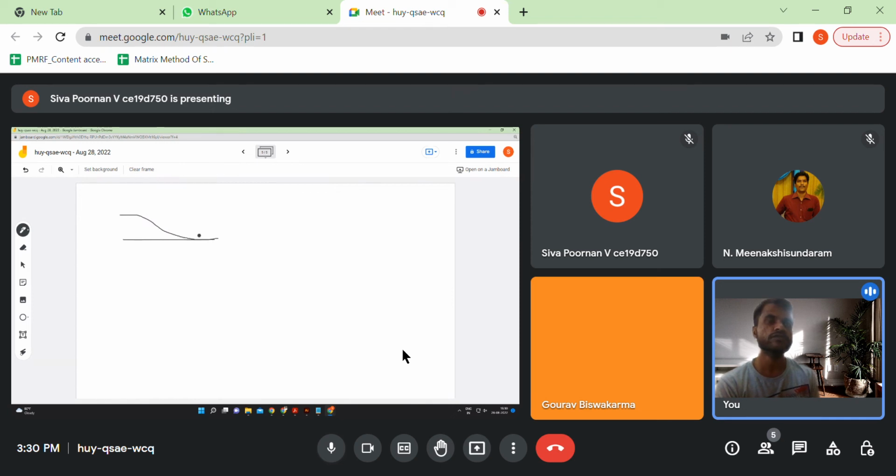Okay, now can you see there is a symmetry about the center? A kind of symmetry, because deformation wise this portion looks very same as this portion as well. Not displacement wise. Displacement is an absolute thing. A deformation is a relative thing. So basically I'm saying that if I take this portion and then somehow rotate it and flip it, can I merge it with this portion? It seems so, because the rotation is 0 at this end and the rotation is also 0 at this end. And you can see that this is just like a deflection of a cantilever, and this portion is also a deflection of a cantilever, right? So basically, if you understand that, then you can solve this problem.